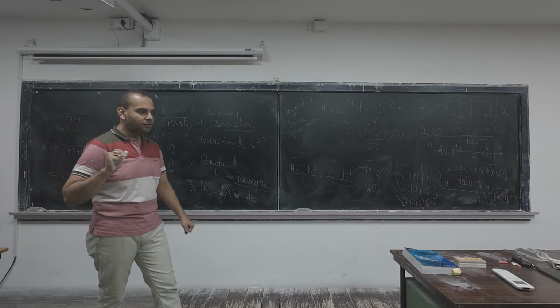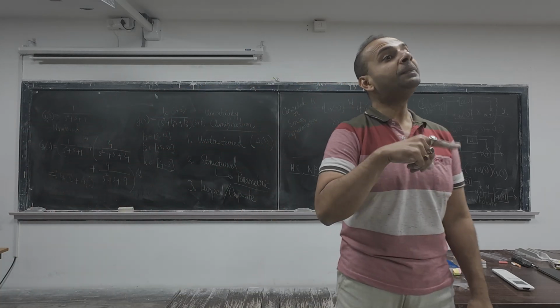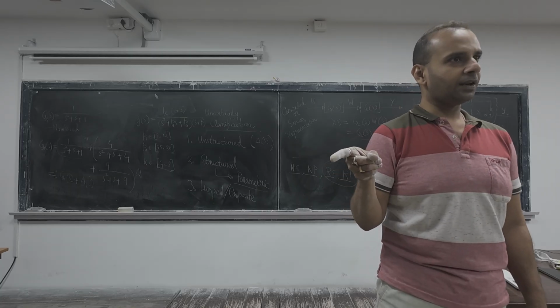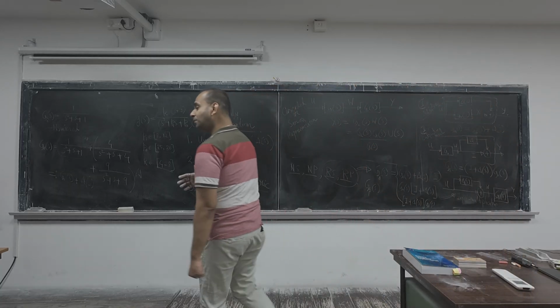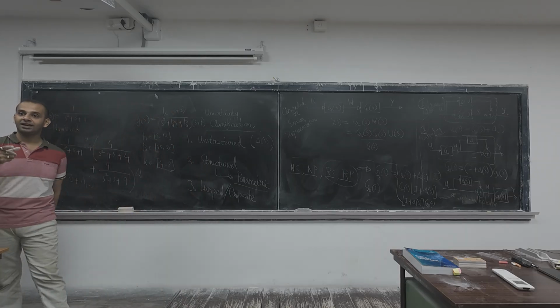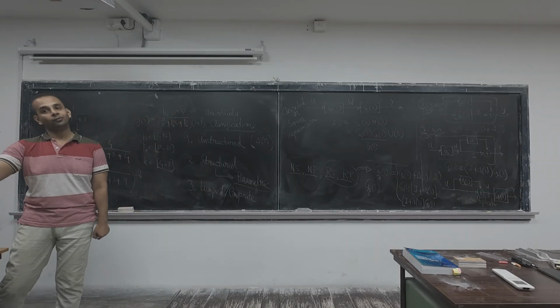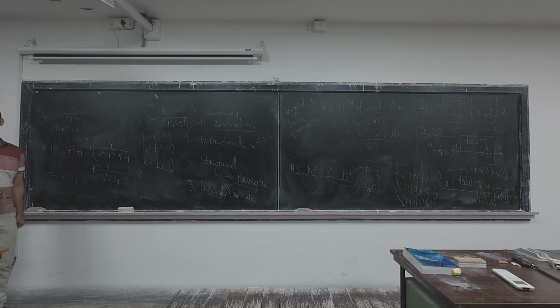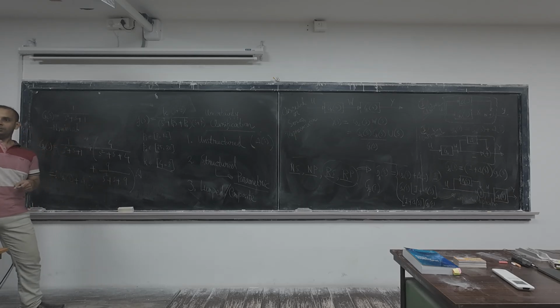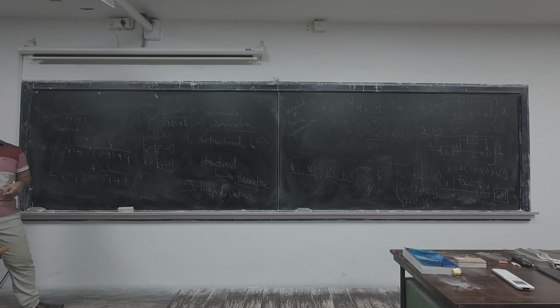Now for any distributed parameter system, we generally go by the PDE model, the partial differential equation model. But working with a PDE model is not at all easy, especially if you have to design a controller based on a PDE model. That will be a nightmare. So often we try to get a linear differential equation model. Then from the frequency response analysis, we try to find out the modes, where it has those omega n1, omega n2 up to omega n, as long as you have a magnitude of sufficient strength.